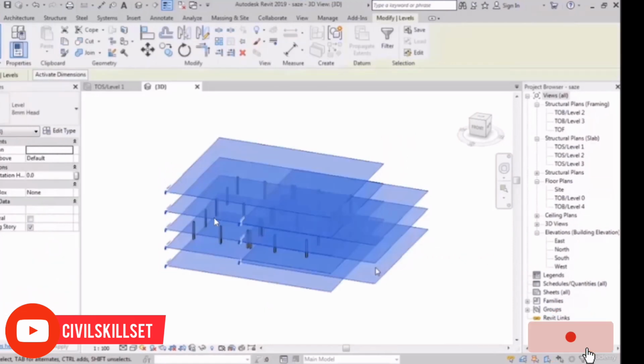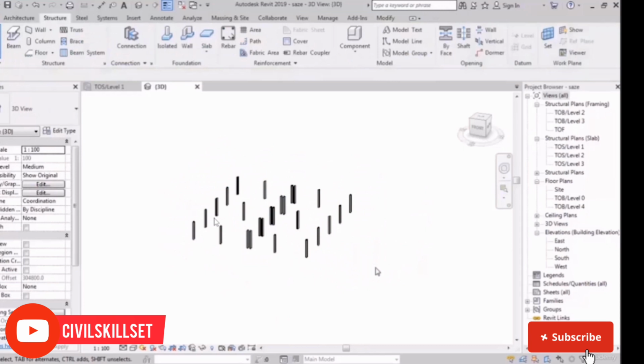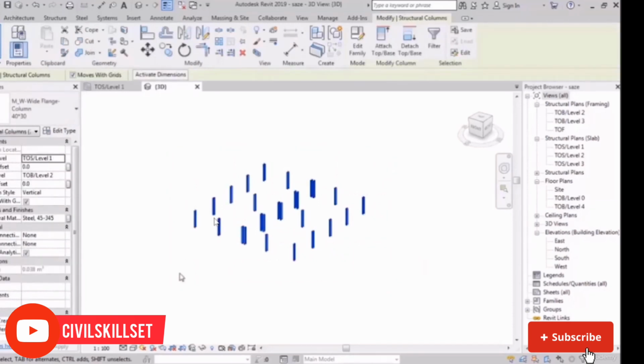We really don't need these levels, which is really annoying. We can just hide them. Now, let's check the height of the columns. I'll select them, and then I can check them here. You should say now, base level. What's the base level? What level should they start from?